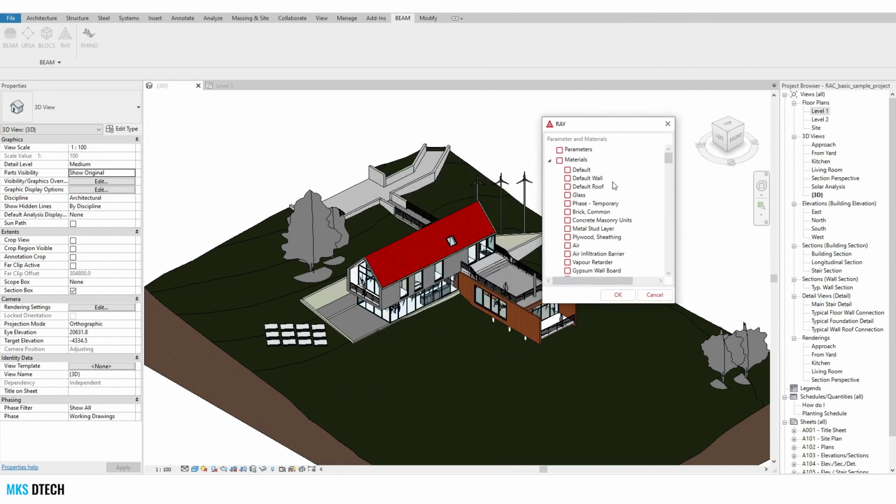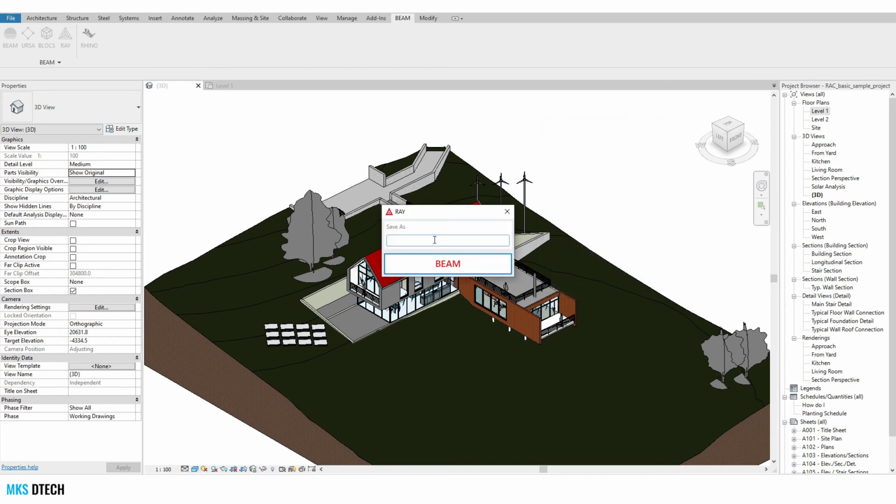So in this case, I have all these materials that I can import into Rhino and assign to a geometry that I modeled in Rhino. So let's say I want to export bricks and concrete. I also want to export earth and asphalt. And by hitting OK and saving this file as materials,